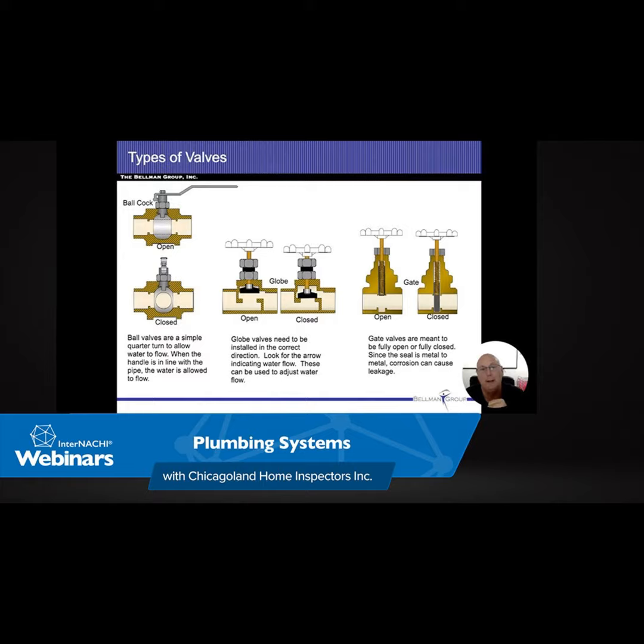You know, the rules have changed since then. We limit the size of the groups now. But out of the 15 people, including myself, only one person caught this. We just saw a pressure relief valve. Okay, that's cool. It's there. And nobody really ended up taking a close look at it. But one person goes, hey, how come this arrow's pointing the wrong way? And then all of a sudden you look at it and you're like, holy cow, that's dangerous. So again, take your time, look at it, even if it's tedious. Do what you can to make sure that it's going to be working right.